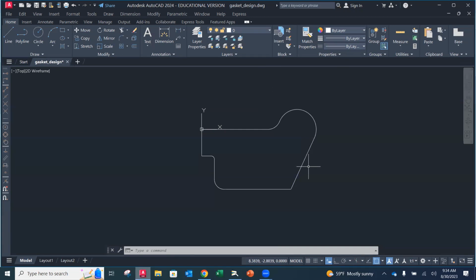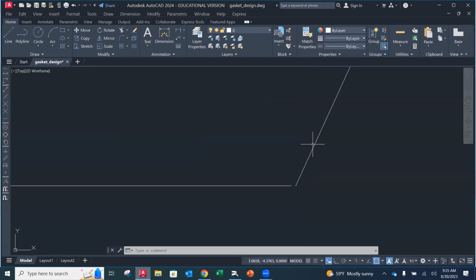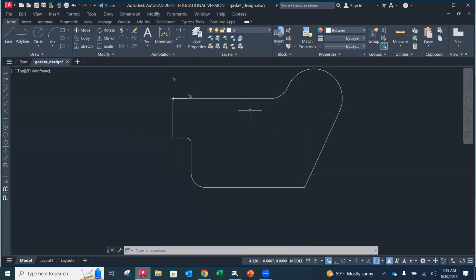Now you can imagine you have a piece of metal and a laser that wants to cut through, but it needs to follow the profile that you created. If there's a break like this, then when it tries to read that DXF, it's going to get an error. Somebody then is going to have to put the geometry back in place. So first of all, a polyline is going to give a nice all-the-way-around way of putting that together.